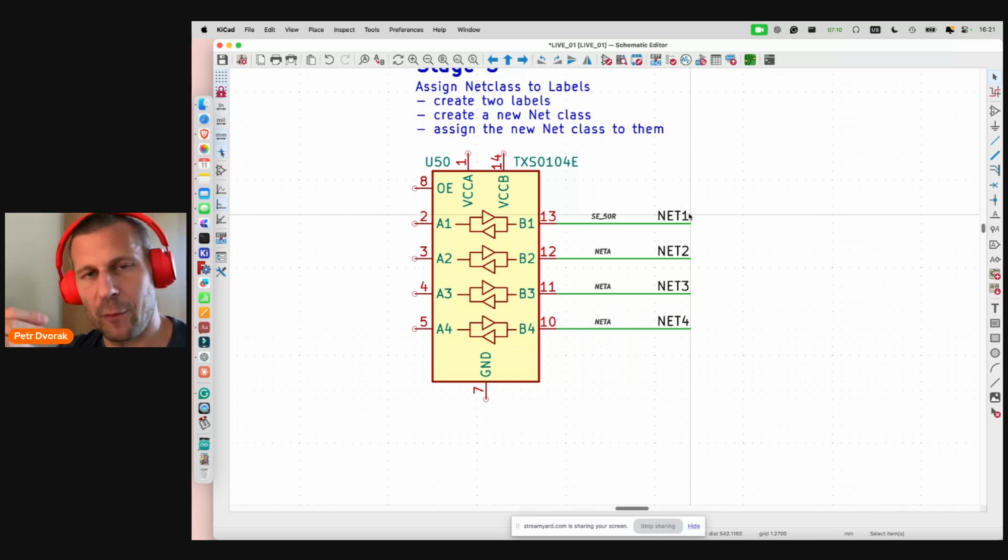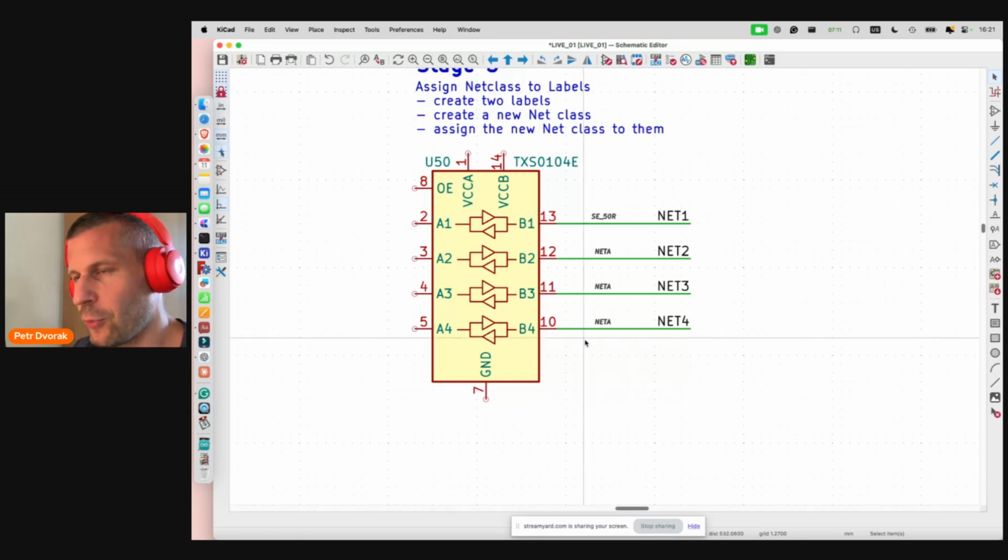When you use, for instance, pin headers, then on the carrier board pin 1 is on the left, but on the other board the connector must be from the bottom side, and usually pin number 1 is on the right. So you need to mirror the connector. To avoid any mistake, I recommend to just copy the entire connector with labels from the carrier board, place it into the schematics of the extension board, and then simply mirror the connector.